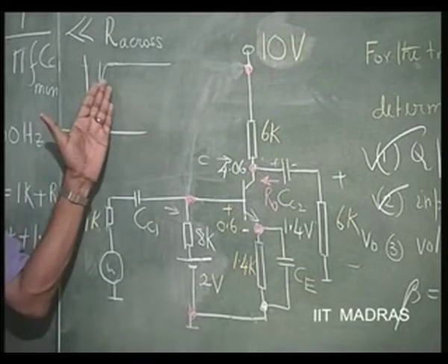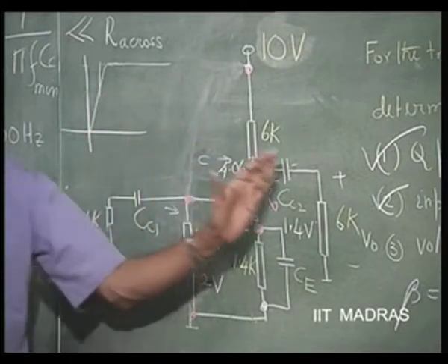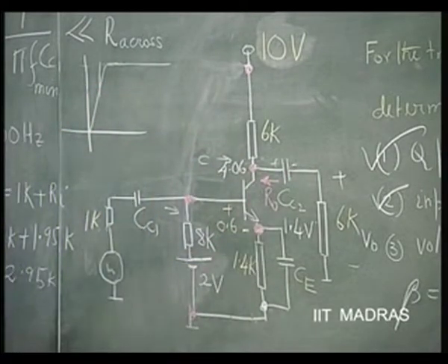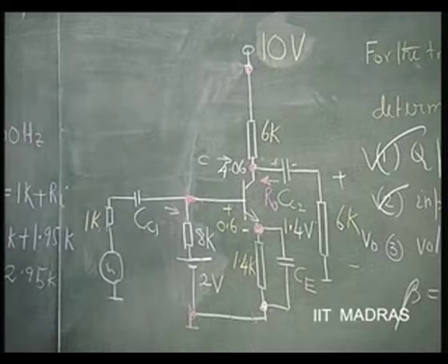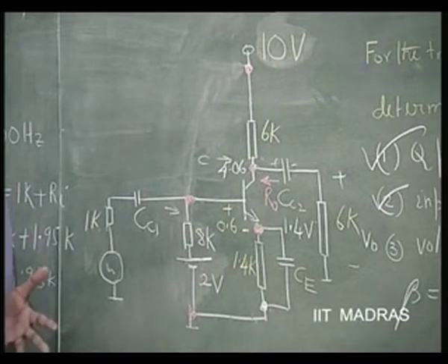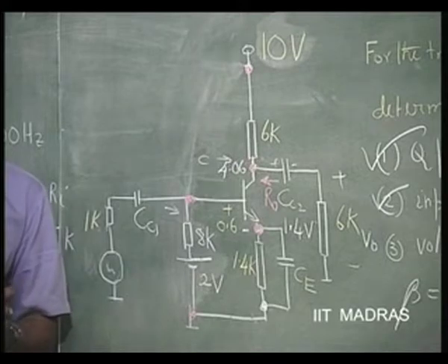Therefore, the lower cutoff frequency in an amplifier is always determined by these capacitors. Now, you can select any one of the capacitors to determine the lower cutoff frequency exactly. Other capacitors are designed to be short circuits. So, that is the way design is done.